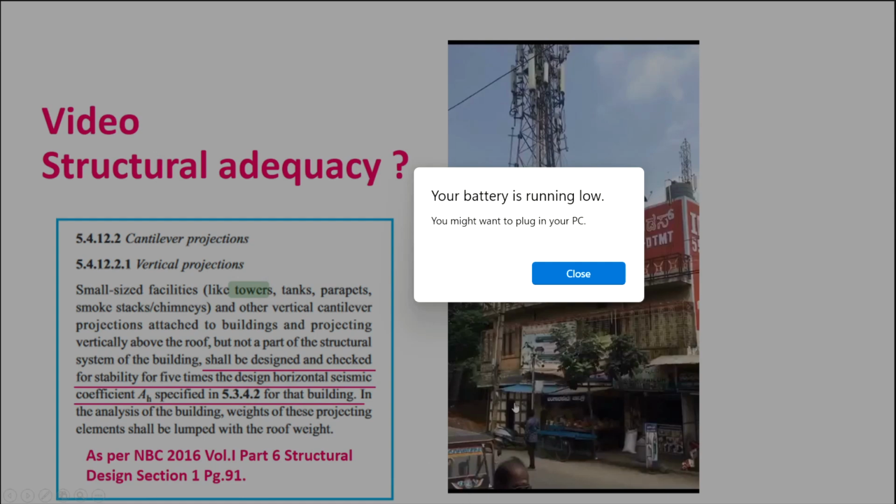Ultimately, just to tell you, this particular structure has fallen down because in this particular building, all these activities they have done, they erected a small structure on the slab itself because it is not an integral part of the column itself. And they have erected the structure and the entire cantilever structure is on it. So this has caused the problem, and ultimately it fell down. So I suppose you must be very careful in case you are planning this type of thing on an existing building.